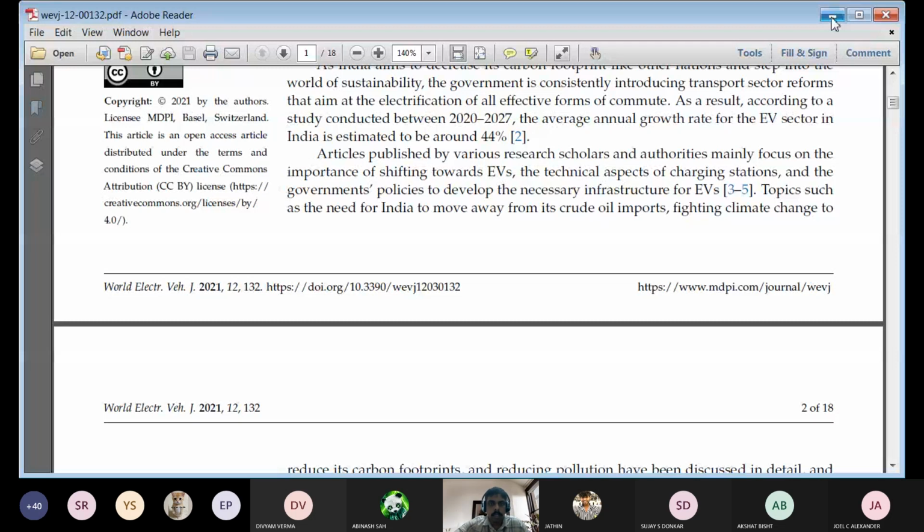Once the numerical is done, we have today discussed the instruments: pyranometer, pyrheliometer, and shaded ring pyranometer for measuring solar radiation. Everything works on a thermopile sensor. It will generate a small EMF in the range of 0 to 10 millivolt, that you can calibrate using the sensitivity of the instrument into watt per meter square.